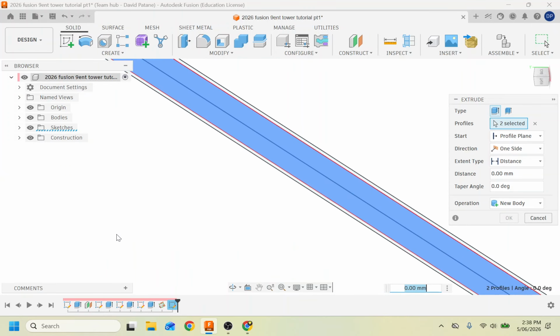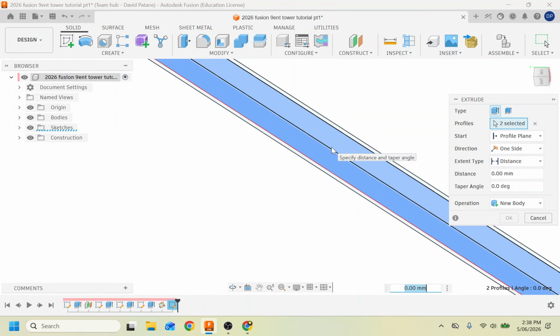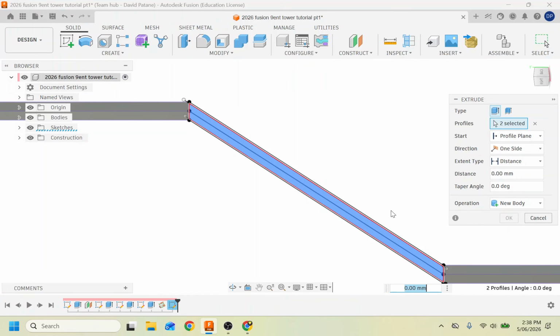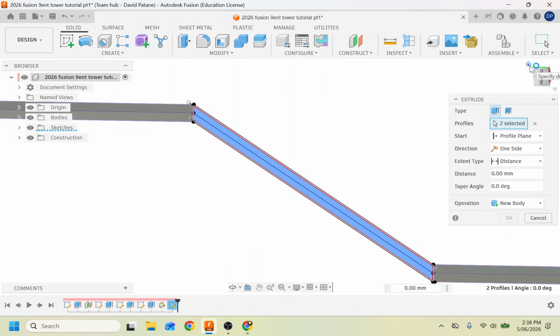Now I know it's slightly larger, and when I look at your design, I'm not going to tell that difference. But where it matters is we're going to eventually get the entire volume of our tower to help us approximate how much material we're using. And what was the number? It was like 5.8, which is about 20% extra material we're using. And once we start getting a lot of these diagonal members, if we keep making that mistake, we're going to be getting a wrong number. So where possible, we'll try to keep it as close as we can to the number we need.